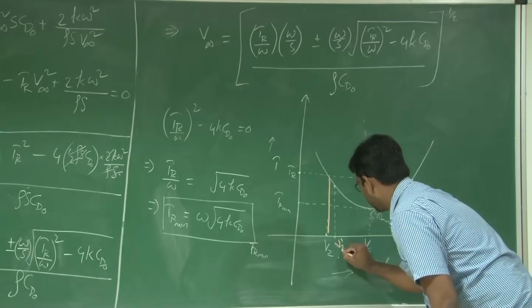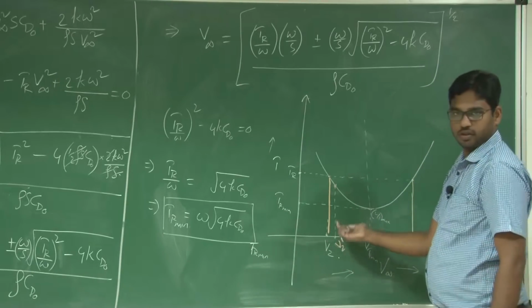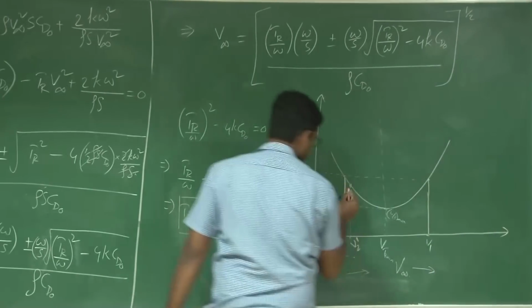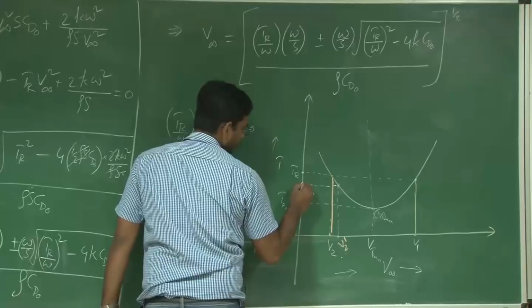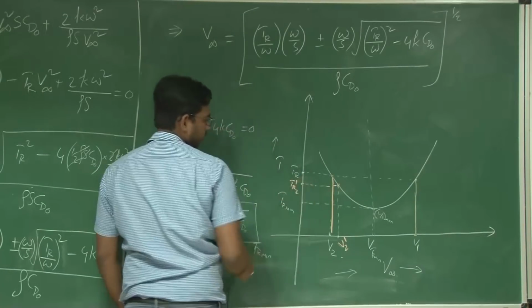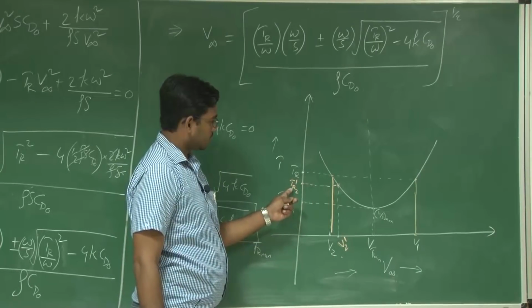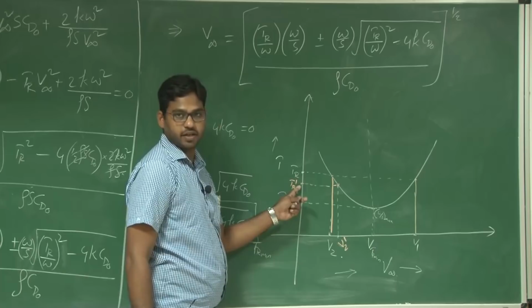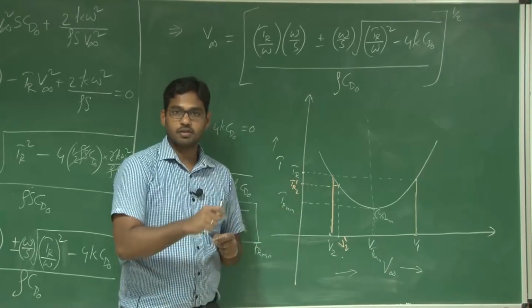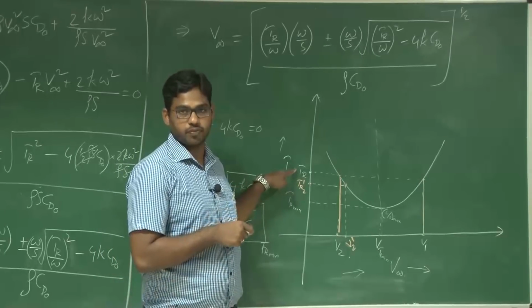Let this be v2 prime. So this is the point that has increased the velocity. So the corresponding thrust required is Tr2 prime in this case. So that means the thrust required has decreased, but the engine is delivering higher thrust and you are not touching the throttle, right.